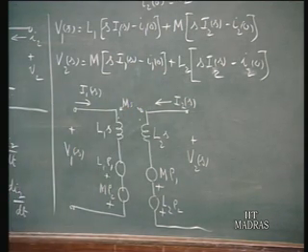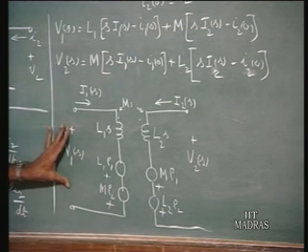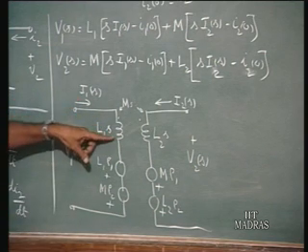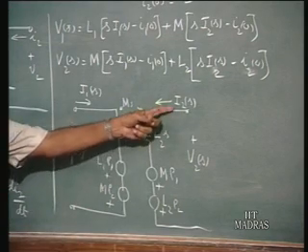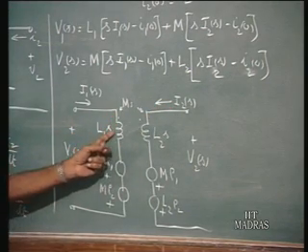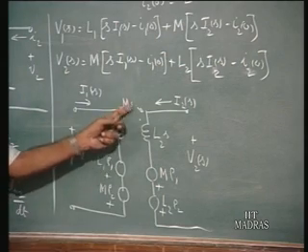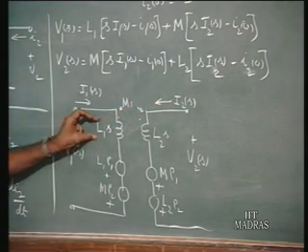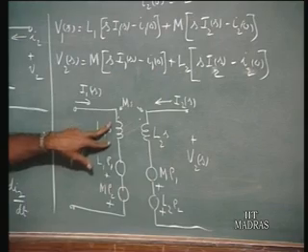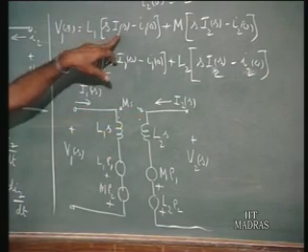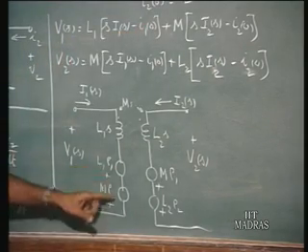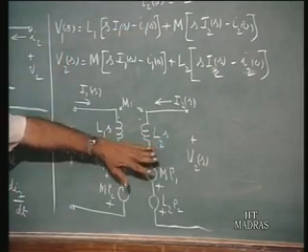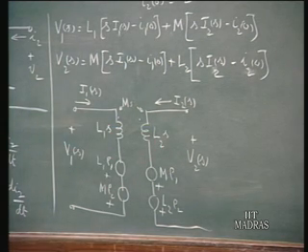So, that means once we write down the transform diagram in this fashion, the terminal voltage V1 of S of this coil is I1 of S passing through L1 of S, which will create a drop L1 S times I1 of S. In addition, I2 flowing to this coil will have a mutually induced voltage here, whose Laplace transform is Ms times I2 of S. So, you have L1 S times I1 of S plus Ms times I2 of S. In addition, representing the initial currents in the inductors, we have two voltage sources. Likewise, the same situation is there in the second coil also.